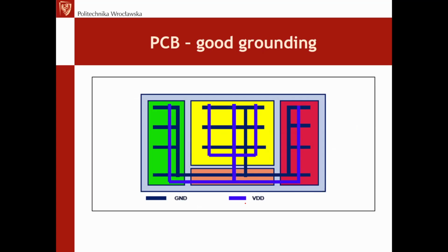The best way would be to connect VDD in this way as well, with this hybrid star/multi-point technique. But frankly, if you don't have such a possibility, if your board is too dense to route the power supply the same way as the grounding, then the power supply can be routed with a multi-point technique.